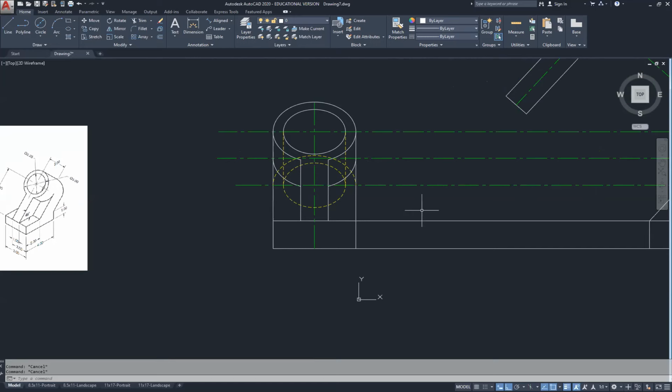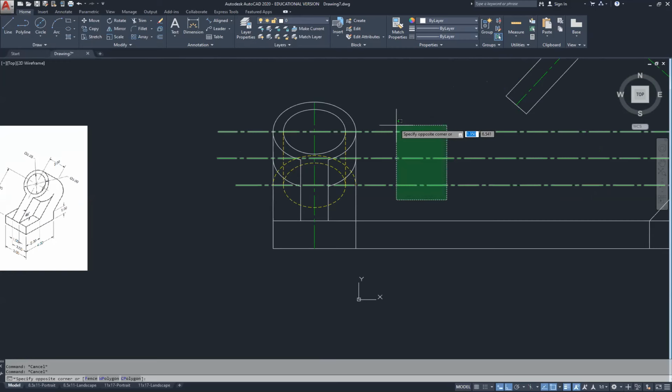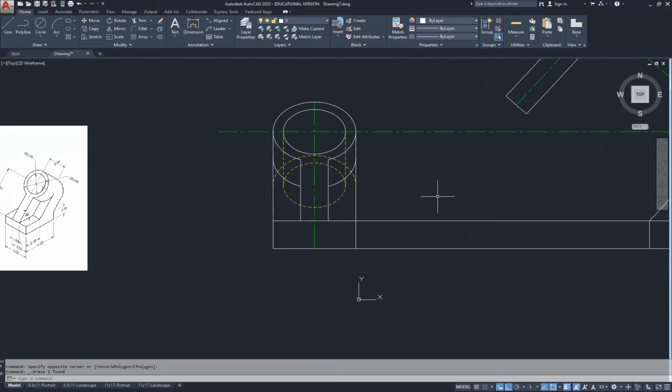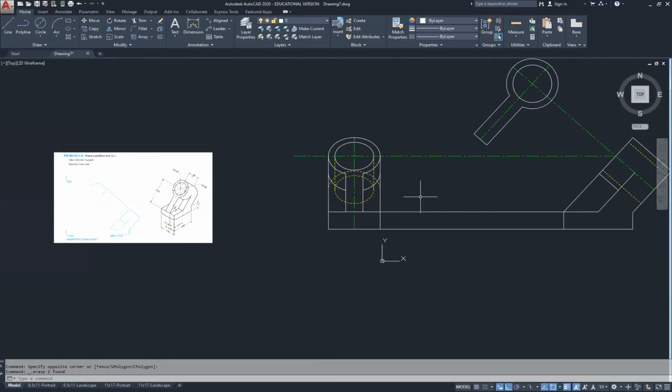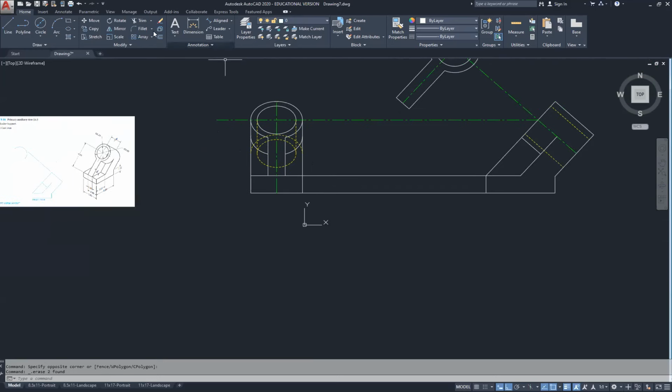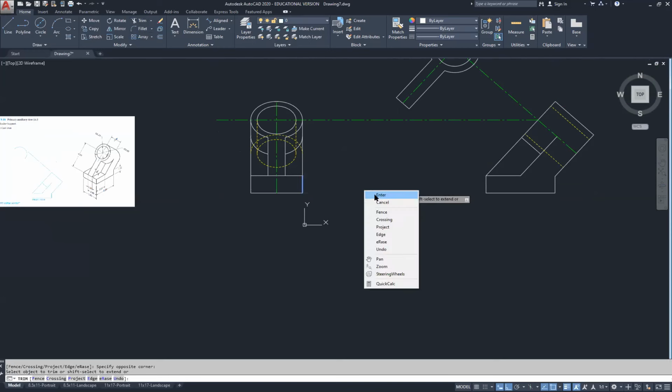So now at this point, I no longer need these center lines. I'll keep one of them to maybe use as a reference. Let's go ahead and delete the other two. Then I'm going to trim out, using this line here as a cutting plane to cut away at those two lines.